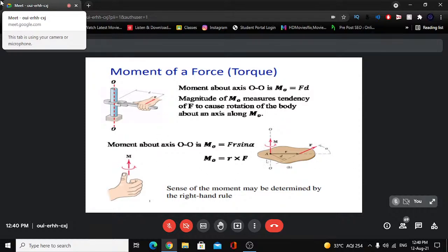So this is a very important formulation. This gives us the correct sign of the force moment vector. I always prefer and suggest that you use this form. But sometimes in easier problems, it is more convenient to get the moment directly using the F and d approach. Their directions also we must visualize and try to understand. In this case, direction will come automatically if you correctly write vector R and vector F. To represent the sense of the moment, the direction will follow the right hand finger curling rule, or it is an extension of the right hand screw rule.